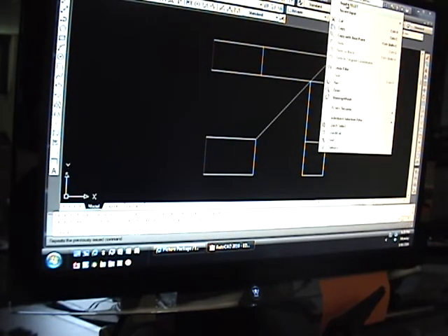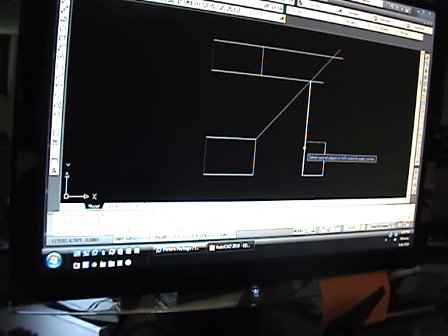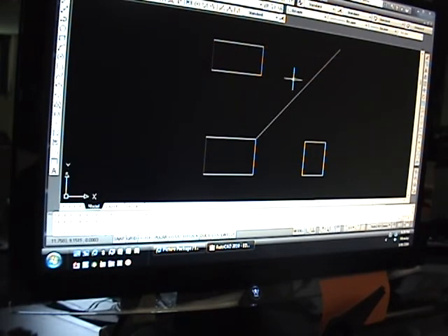And fillet each one of those. Probably go ahead and trim the tops out too. Now we can trim the top. Well, maybe you need to erase them. Okay, because we have projected all of our views. And as you can tell, there was a relationship between each one of these views. This is what we call third angle projection.